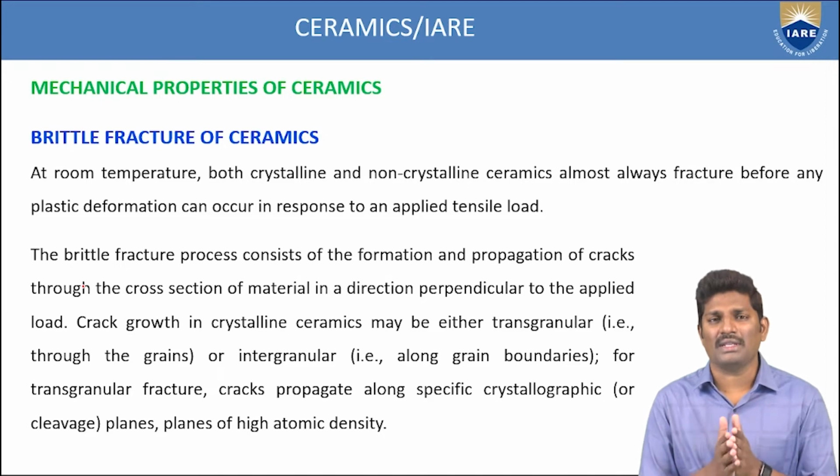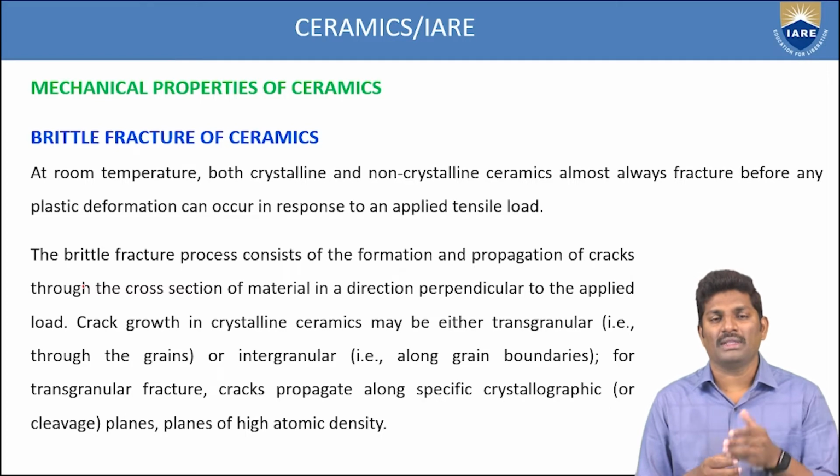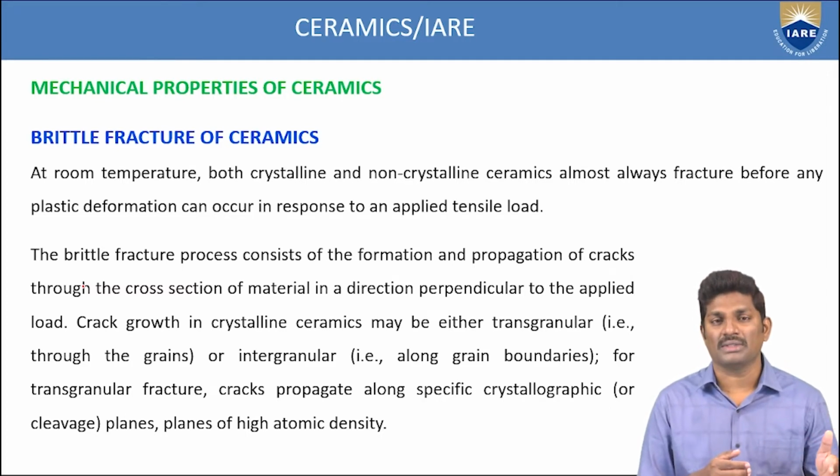Any material in general, if you consider, will break after plastic deformation. But in this case, the ceramics, whether crystalline or non-crystalline, are getting fractured before the plastic deformation. That means in between the elastic and plastic deformation, the ceramics are fractured at room temperature. So this is a very important point you have to note down.